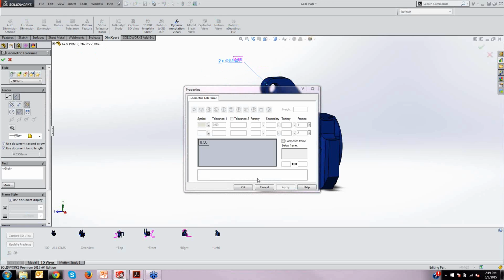And I can easily add some GD&T to this particular dimension. So in this case, some true position, setting my tolerances, and calling out any datums that I need to. One of the nice things about doing this is that, say I call out a datum that doesn't apply or is the wrong datum. SOLIDWORKS is going to tell us that datum Z has not been defined.